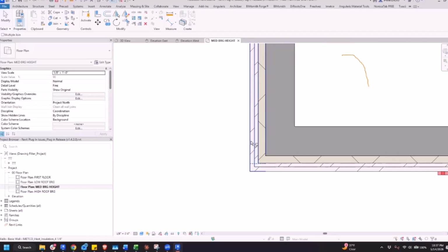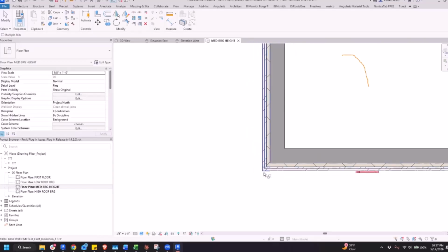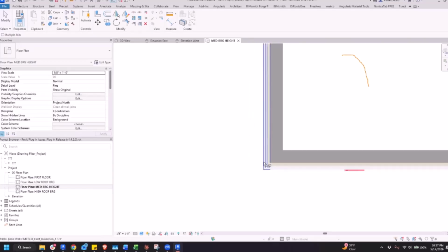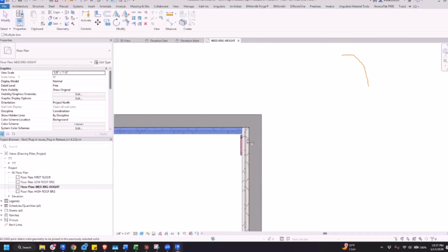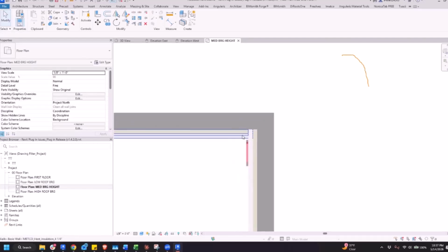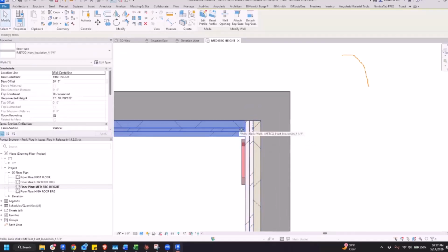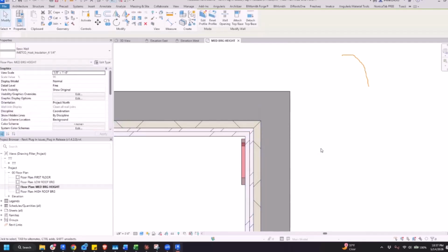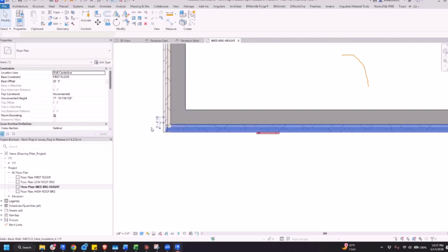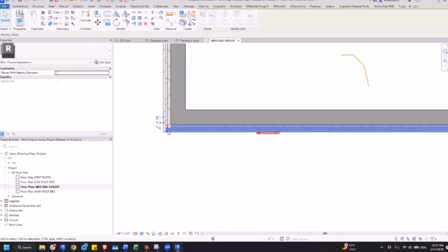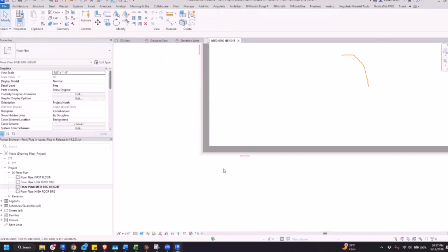That wall is only a feature on 2025 and up, right? 2024 and up, Jonathan. That's not on 2022. We cannot create slanted walls after 2023, I think, or 2022. I don't recall the exact year, but in previous versions of Autodesk Revit, you were not allowed to create angled walls. I believe it's a new feature on 2025 maybe or 2024. And since we're not using that as a reference, then the tool is not designed to work with slanted walls.